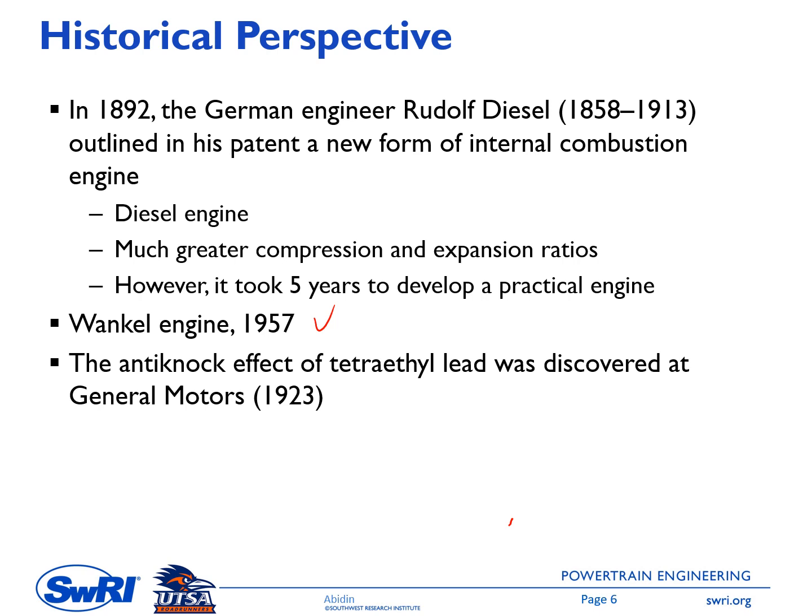A good thing about this rotary engine is its compactness, and it's also simpler because it doesn't require a valve train system and so on. But the disadvantage of this rotary engine is its higher surface area, and you know that higher surface area increases the wall heat transfer and thus gives a lower engine efficiency.